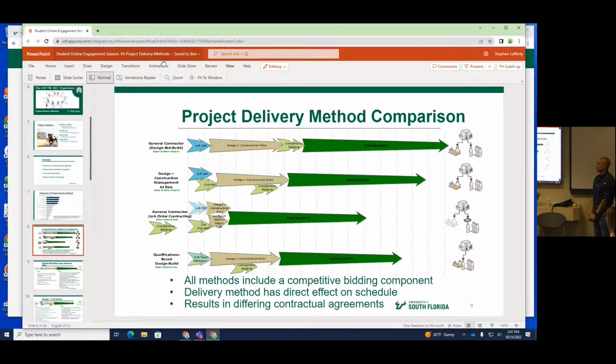We'll get into that. So then a delivery method called construction manager at risk with an architect. Here the owner has a contract with the architect, and the owner has a contract with the construction manager. You have the same thing with a design construction manager, except the architect and the construction manager are hired at the same time. Whereas here, you hire the architect first, then you select a contractor based on the lowest bid. Here, you bring a contractor in at the same time, and then they work together through the design and through the construction documents. You do competitive bidding to the subcontractors, and that's actually the way the Honors College is being delivered.